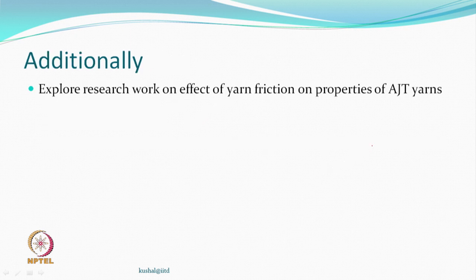So, a little bit of confusion, whatever it was on the friction, what it does to air jet textured yarns, other than what we were looking at with water. Maybe you can change the interfiber, inter-yarn, filament friction by adding different kinds of spin finishes, different amounts of spin finishes.